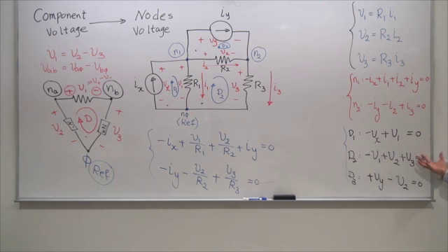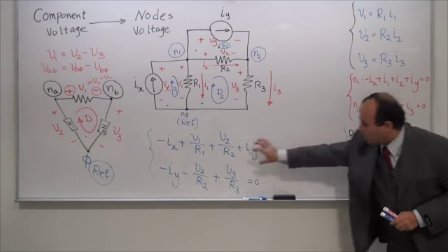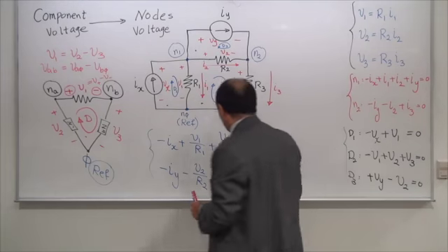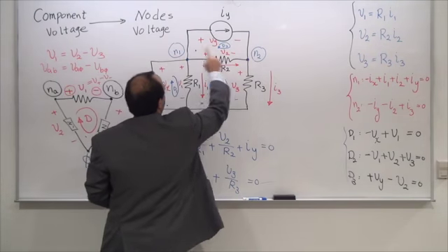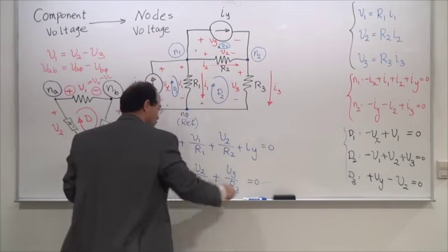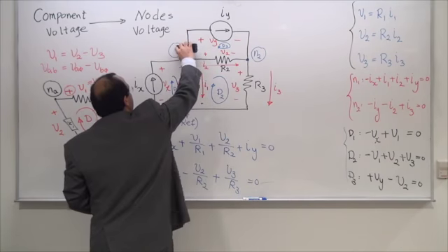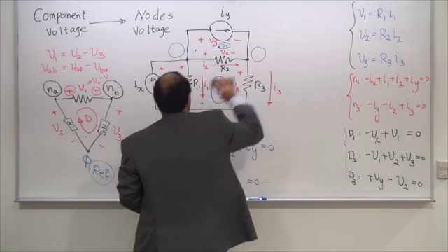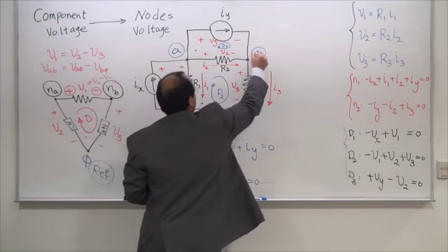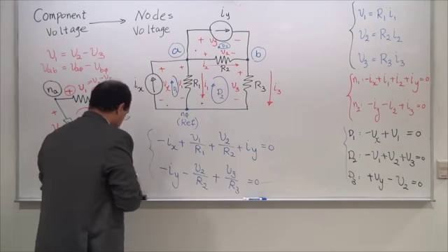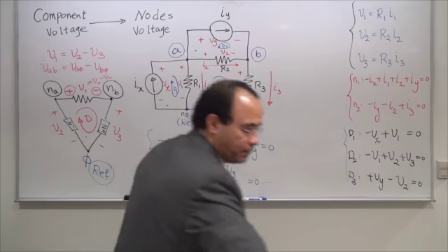If I do that transformation I was just talking about, I'm going to actually take care of this KVL law at the same time. So let's put the KVL law in. Let's do the transformation. For V1, I'm going to say VA minus VB. Let's label this now in a different way so that we don't mix them up. I'm going to label this as A, I'm going to label this as B, and let's begin.